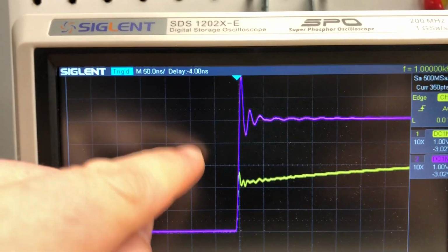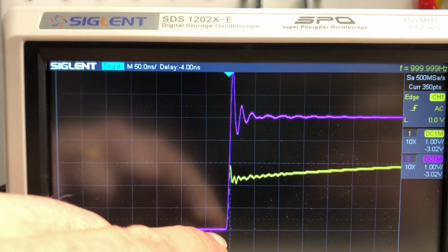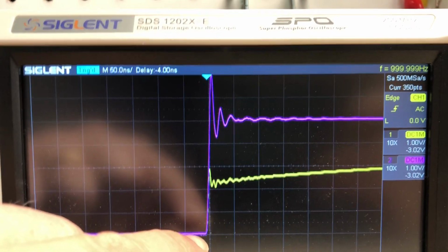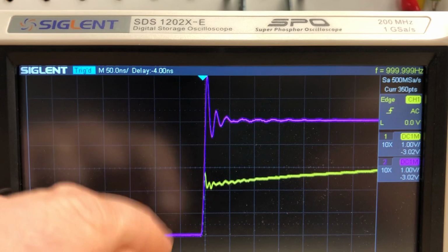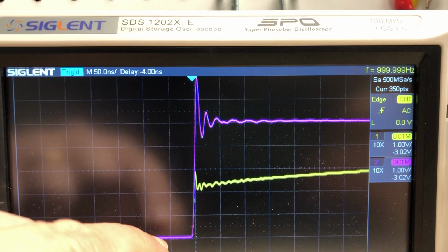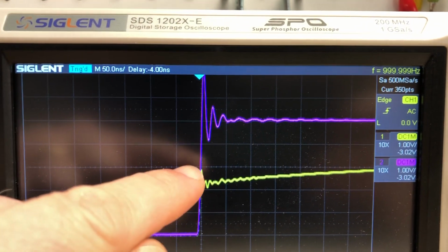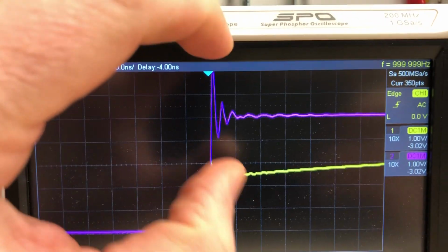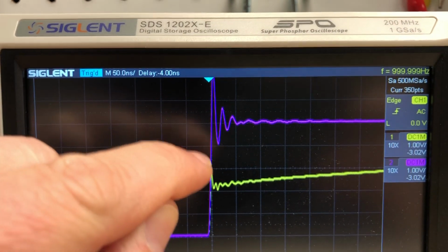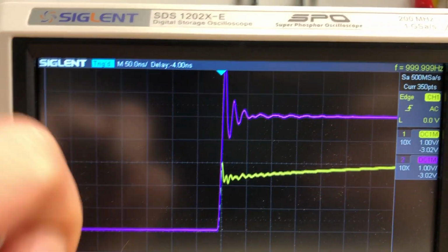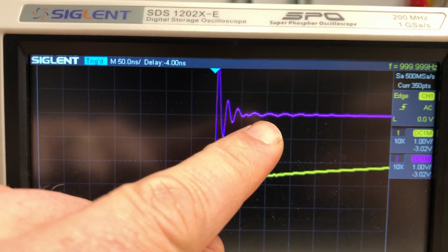This is a very common situation with a very sharp electronic signal. What's happening here is that if you look at the Fourier transform or the Laplace transform of an instantaneous increase, it's actually composed of an infinite series of much higher frequency sine waves. And because it's also Laplace, we also have this exponential component. So we have this envelope of exponential attenuation of this high frequency sine component of that signal. Something that seemed as simple as just going from 0 to 5 volts is actually quite complicated.